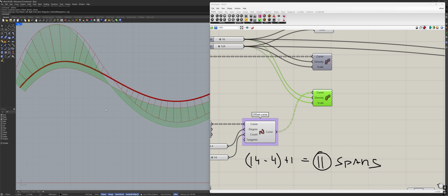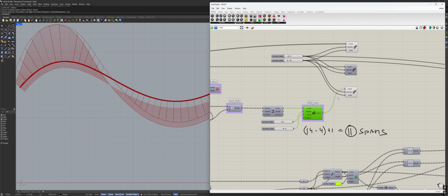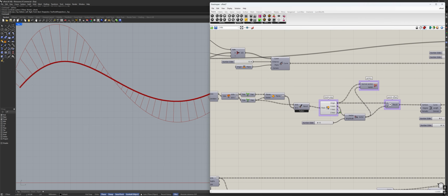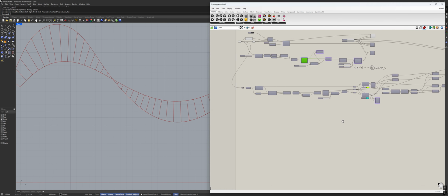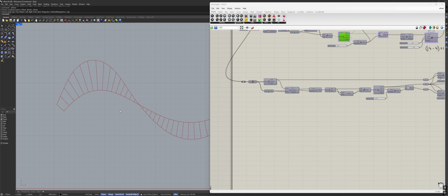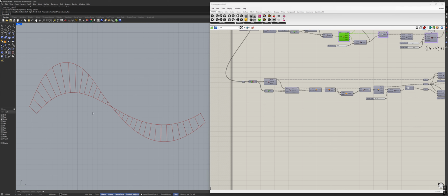So we talked about the automatic approach, but I said there are two distinct ones. The second one is an offset. So let me hide this and hide this. And now we go to the next method, called CV offset in Alias. The CV offset method works differently. It takes the control vertices of your curve, not the points on the curve, control vertices.